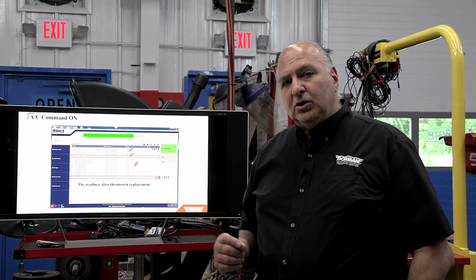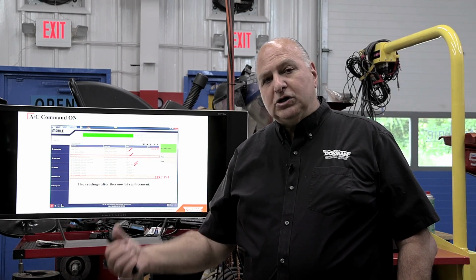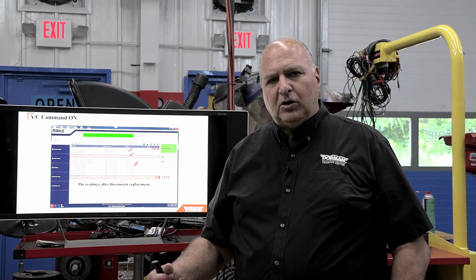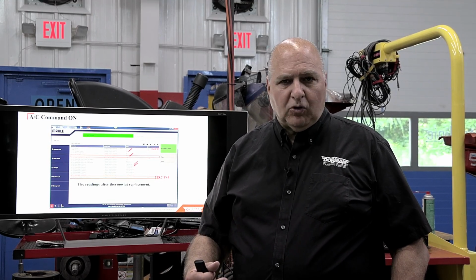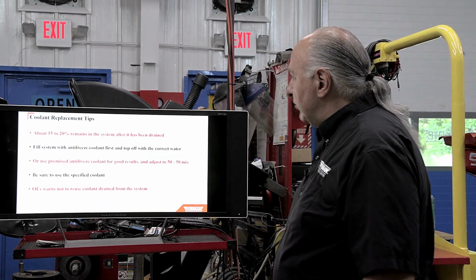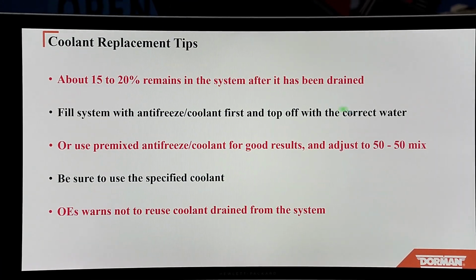In fact, if you watched our Lunch and Learn a couple of years ago on Tesla, well, you would have seen that sometimes when you want to do a coolant system or you want to do an air conditioning service, it's not as simple as a regular vehicle of hooking up. You're either going to have to go into their display or into their scan tool toolbox because there are certain valves that you would need to open or close or command before you can do a coolant system or an AC system service.